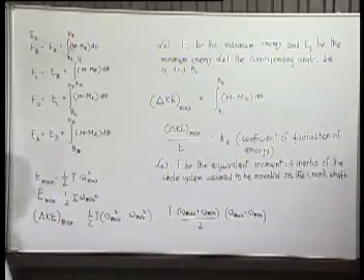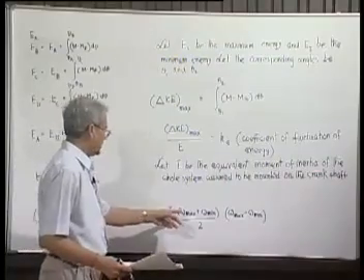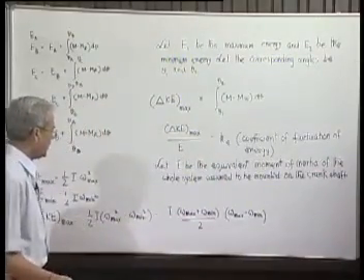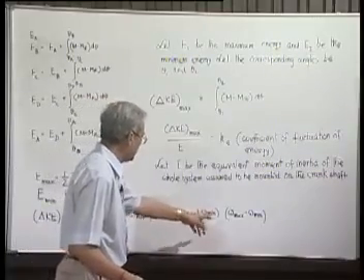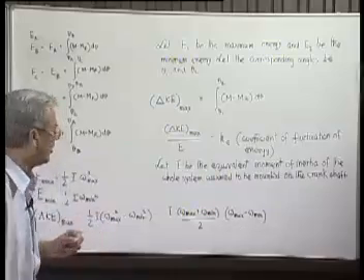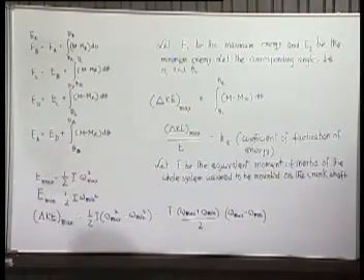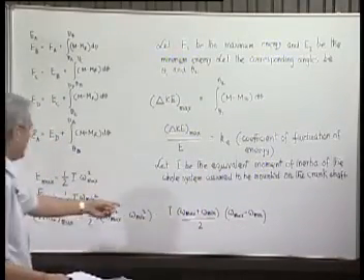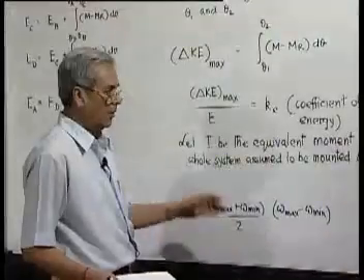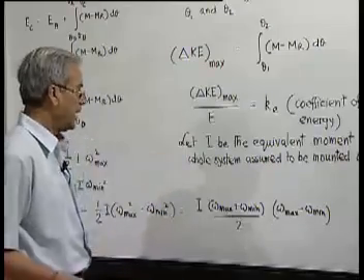Now, there is a fluctuation of speed obviously. What we can do, this omega max plus omega mean, their average, in most cases since the difference is very small, can be considered to be the omega average. So, this can be approximately written as omega average, or the average running speed of the engine.